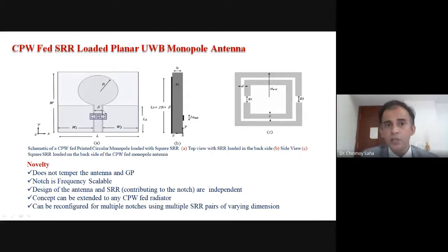That will be covering the entire frequency range. This tiny set of resonators, which are sub-wavelength resonators, are also called magnetic resonators, because the magnetic field of the propagating electromagnetic signal basically excites them. Those resonators are placed over here, and at their resonance frequency this structure acts like a notch filter.